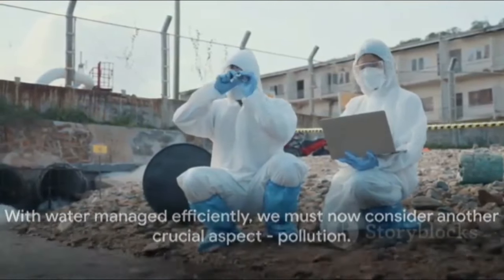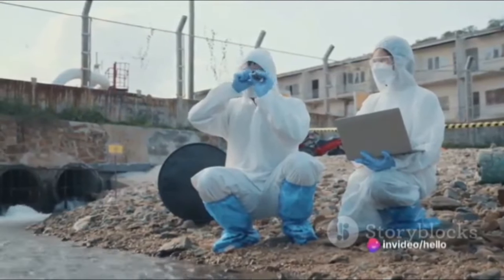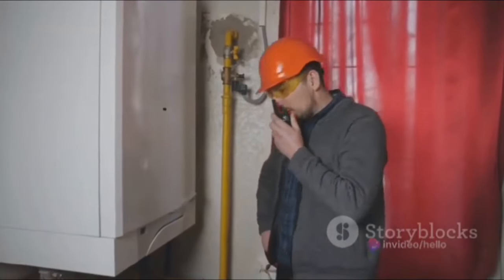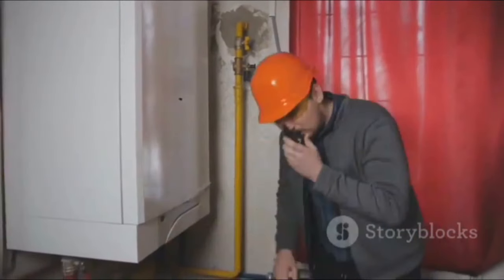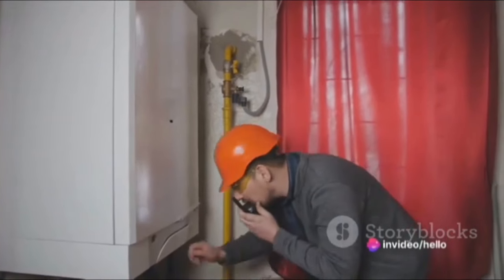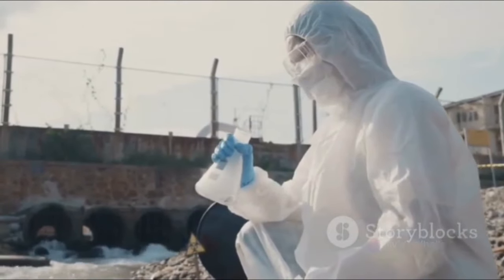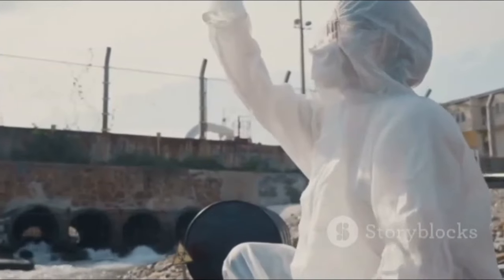To ensure the water is thoroughly clean, it undergoes a disinfection phase. This usually involves treating the water with chemicals, heat, or ultraviolet light to kill any remaining microorganisms. Once disinfected, the water is then treated with coagulants, chemicals that cause the remaining particles to clump together for easier removal. After this final cleansing, the water is now ready to be reused within the power plant.